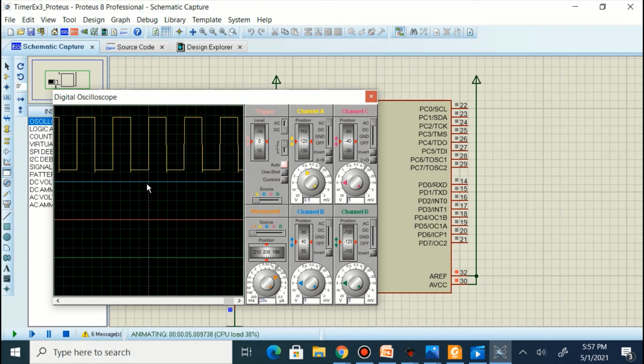We can observe the time period for one cycle is approximately 4 slots, which we multiply by 20 microseconds. So we can say it is a little less than 80 microseconds. If we calculate the time delay, because in this case the timer count is loaded with 00, it is going to count from 00 to FF hex and then roll over.